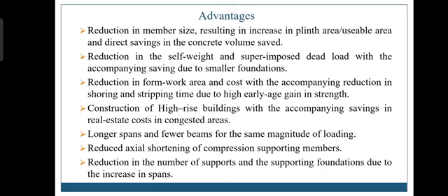Let's see the advantages. Due to high strength, it reduces member size and saves concrete volume, and due to its lower self-weight, the superimposed load is less than usual concrete load. Due to high early gain in strength, it reduces time. It reduces the number of beams, and longer spans can be used, which leads to a reduction in the number of supports and supporting foundations.